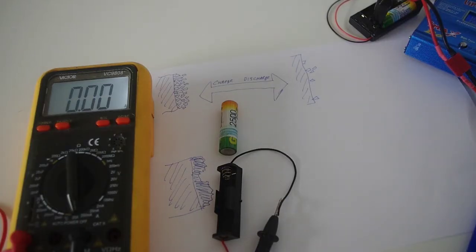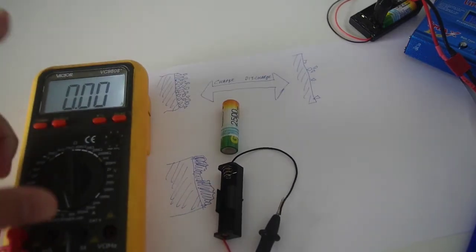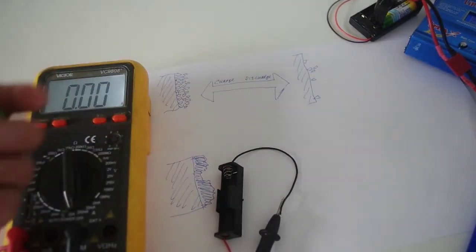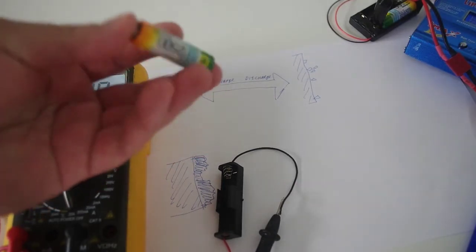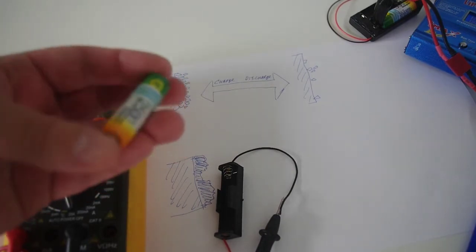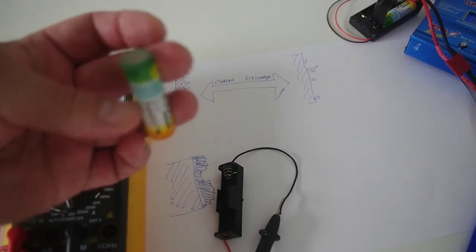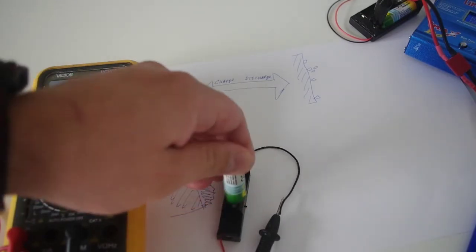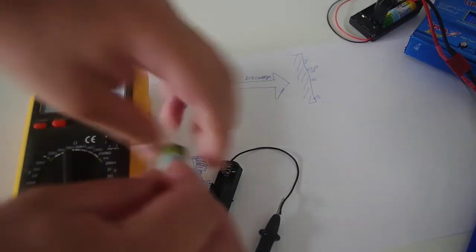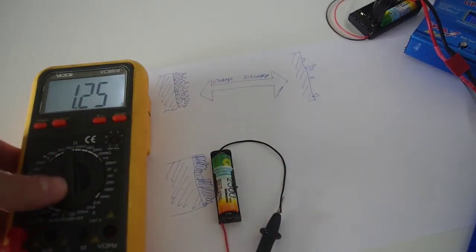So what you need to do to recover the cells is discharge them fully one by one. I will use my multimeter for this in current measuring mode. Again, they were previously discharged in NiMH. You can do this in some other device, in some other load, perfectly, if it is designed for just one cell without too much digital electronics. And after they are fully finished, you just need to short them with the multimeter in current measuring mode.